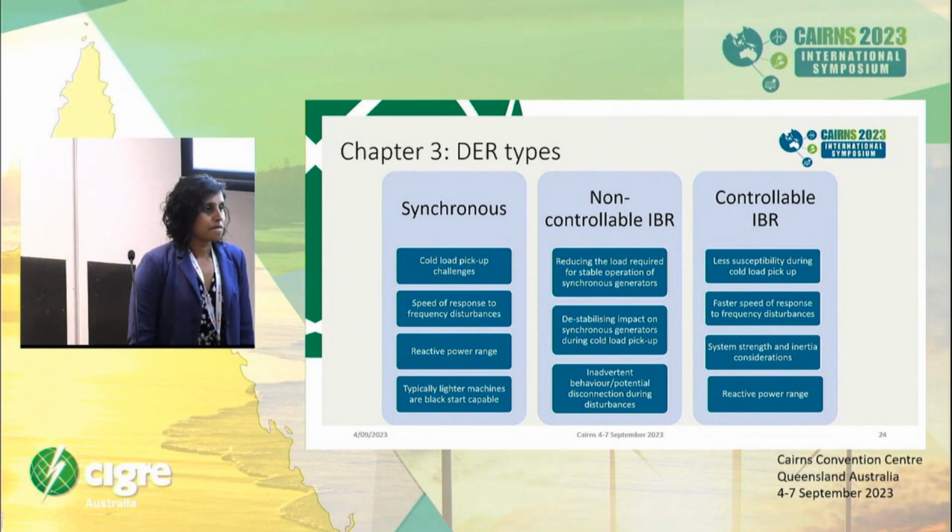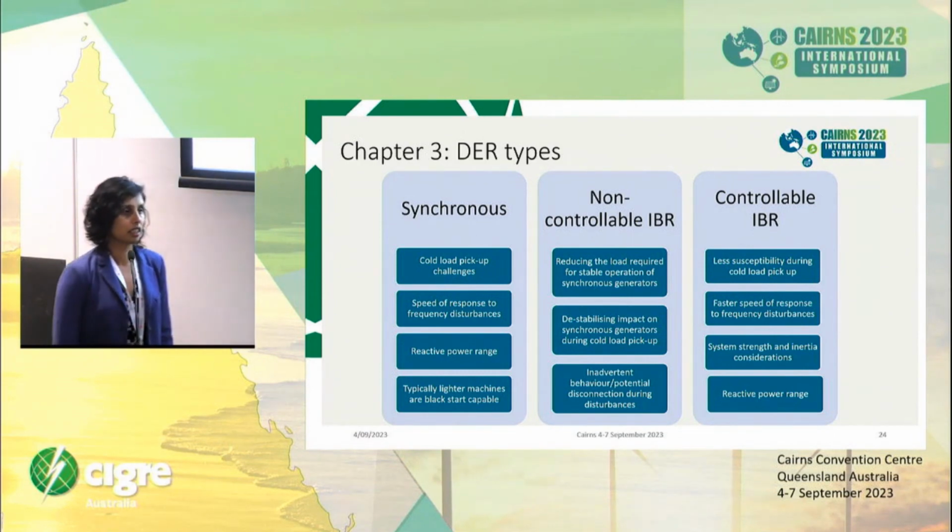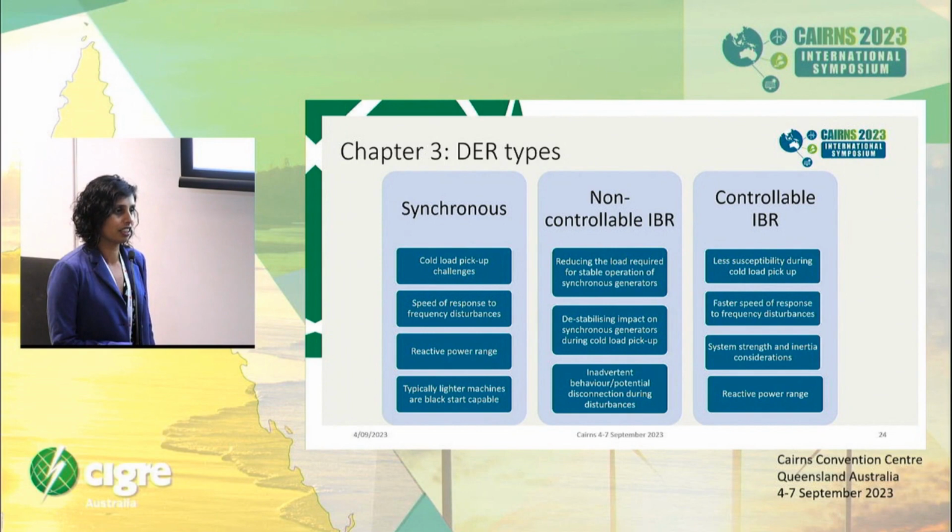When we talk about black start, we talk about black start paths. And traditionally, we had these paths to get energy to the auxiliaries of coal-fired stations, to start them up. Correct. In the power system of the future, we don't have to do that anymore. Have we thought about alternatives to that traditional black start path? Because I see you still refer to a black start path. I don't think we need those anymore. But we also have to consider the number of people you have in the room to be able to manage all these little islands that you're going to form.